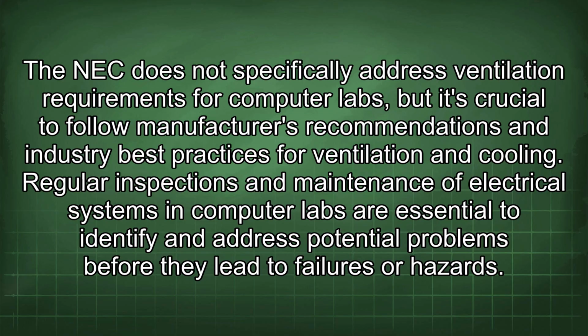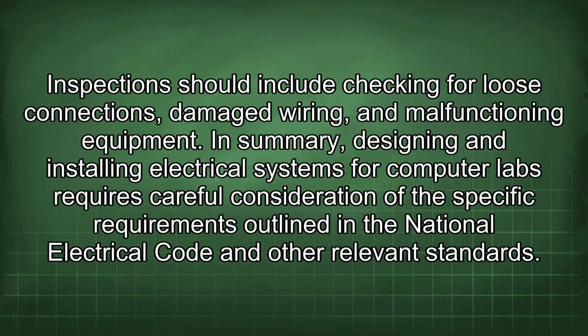Regular inspections and maintenance of electrical systems in computer labs are essential to identify and address potential problems before they lead to failures or hazards. Inspection should include checking for loose connections, damaged wiring, and malfunctioning equipment.